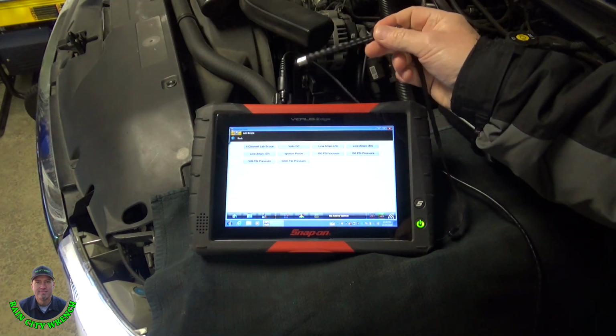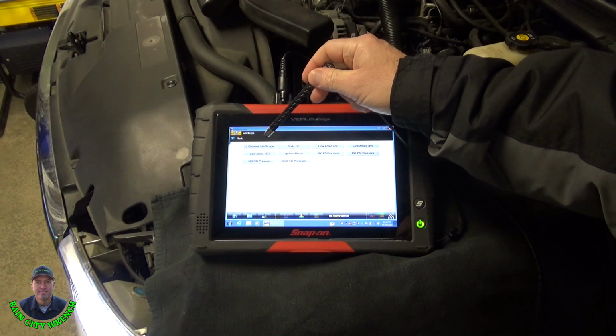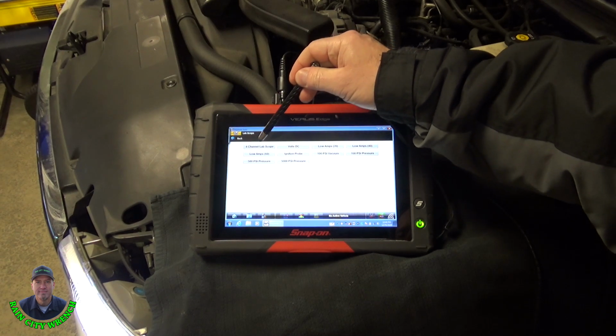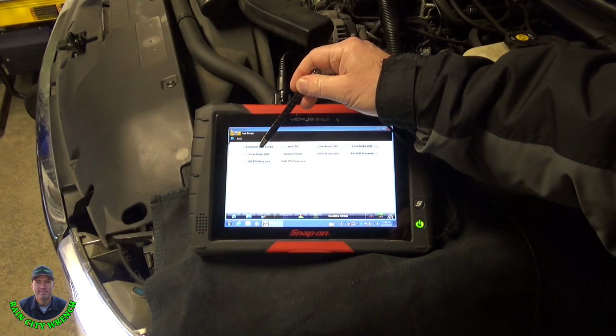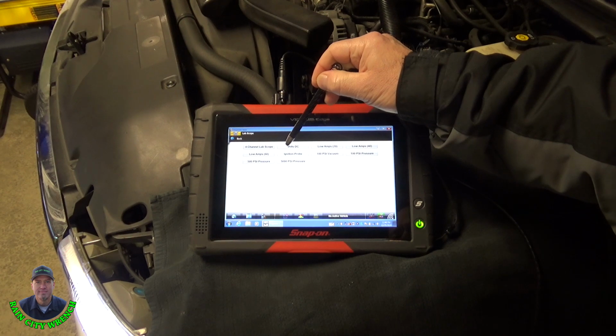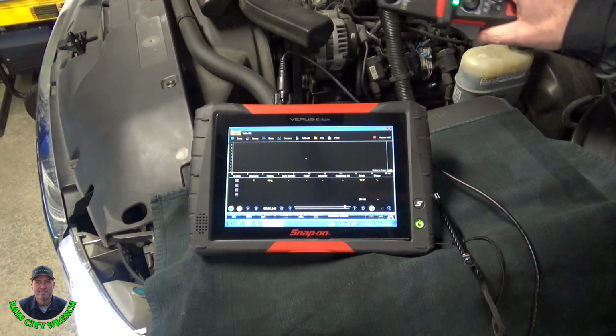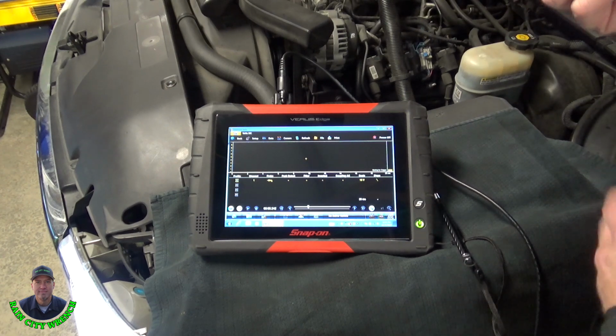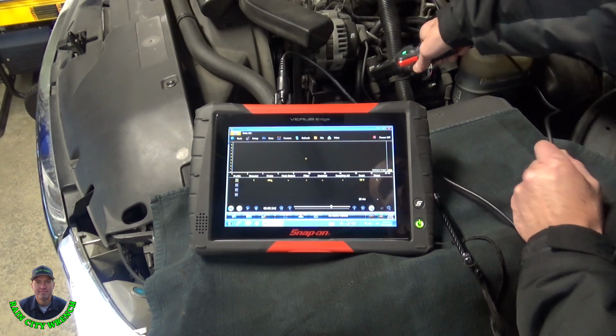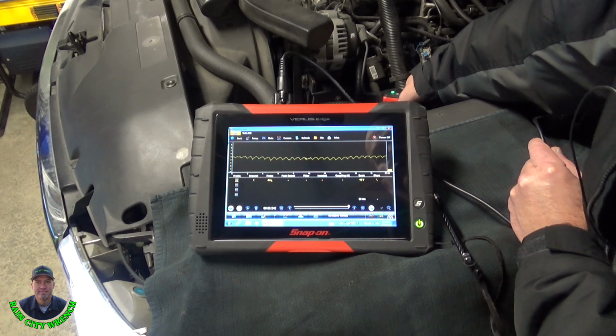This time, a diode pattern. We're going to want to look at it in a quicker time frame, so we're going to go into 4-channel. Well, we'll go into volts DC. Either one will work, or 4-channel. So let's connect this to the charge back lead, and on this one, it's really easy to get to. It's just right here. We'll just hook it up.